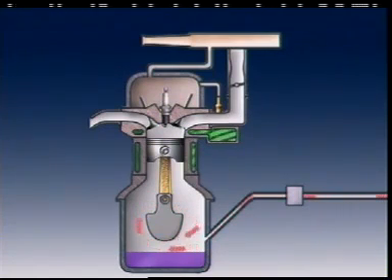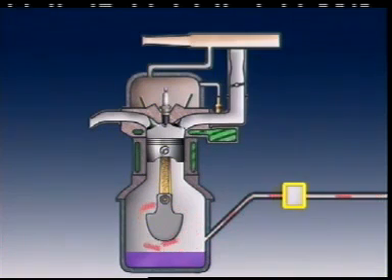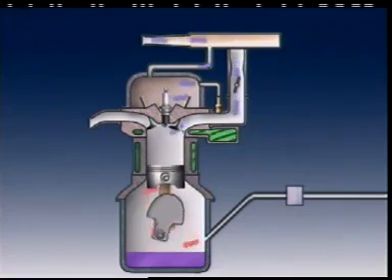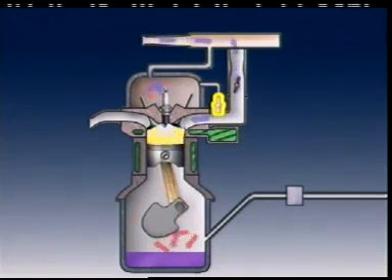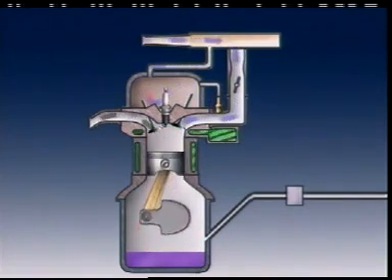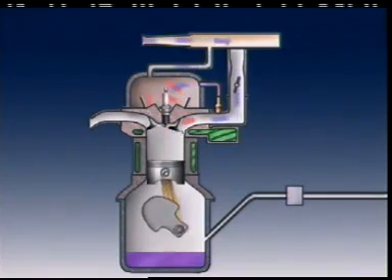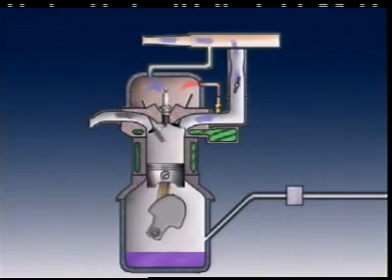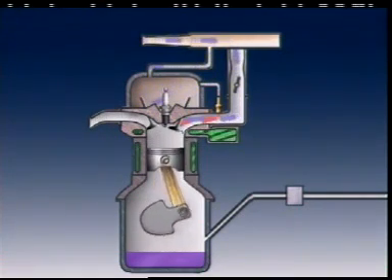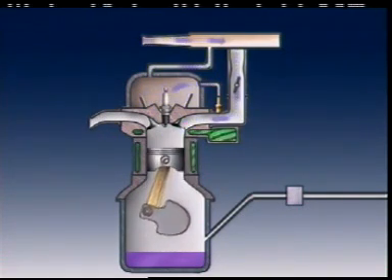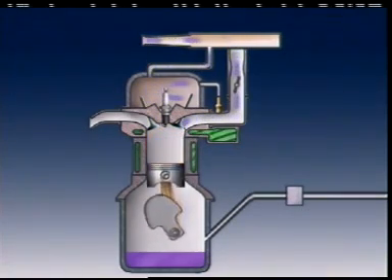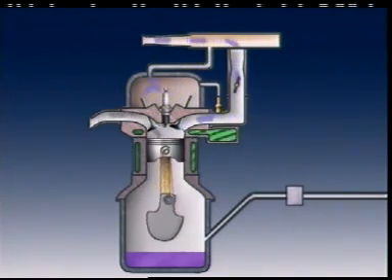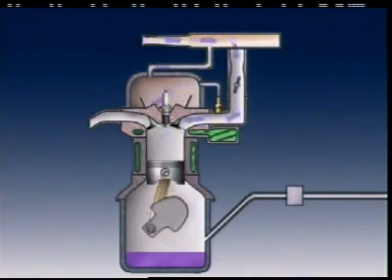When the temperature of the fuel in the tank increases, fuel vapors are forced along the vent line past a liquid check valve and into the crankcase. When the engine starts, the positive crankcase ventilation system flushes vapors out of the crankcase and into the intake manifold, where it joins with the inlet air-fuel mixture. Once in the inlet manifold, the vapors are drawn into the engine, where combustion can convert them into carbon dioxide and water vapor.